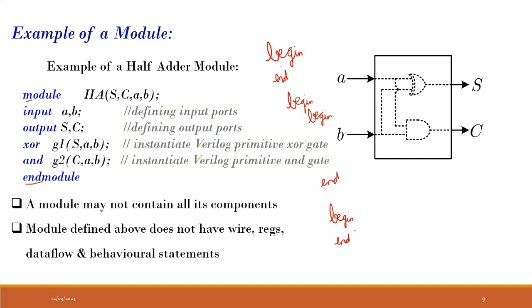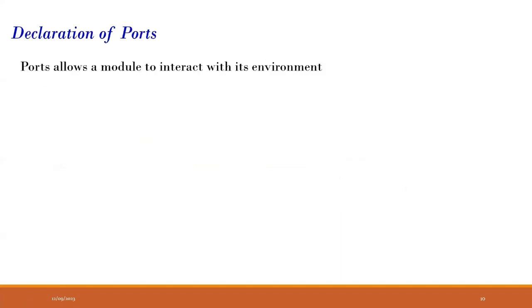Okay, it will automatically go, but here it will not do. You have to write. So I'd recommend whenever you start writing anything, you also write the end part and then write the code over here. Don't just write begin and then do if A is less than B, something like that, and then you might forget to write end. So whenever you write a begin, you write an end immediately. And then between the begin and end, you write the functional code. This is just a simple thing to get rid of unnecessary errors which might pop up. Okay.